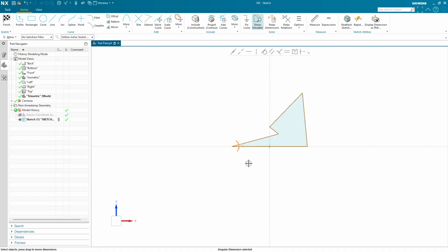I gotta get rid of this now. If I say these must be perpendicular, it makes them perpendicular. And it didn't let me do it the first time because I had put in a constraint that they would be 15 degrees, and perpendicular is not 15 degrees, so there was a conflict there. But now, through the use of a relation, I have made these two things perpendicular to one another.